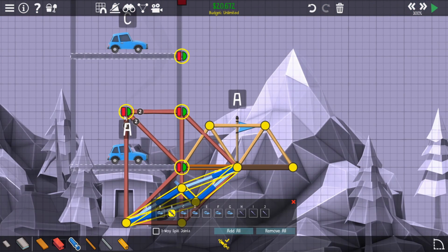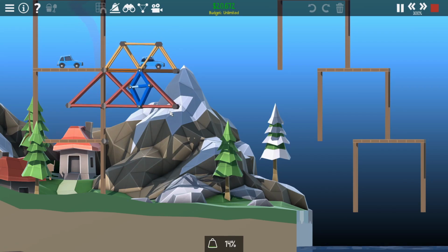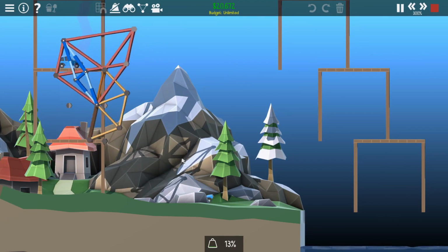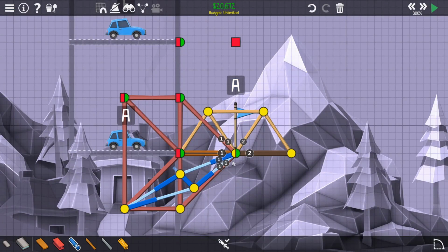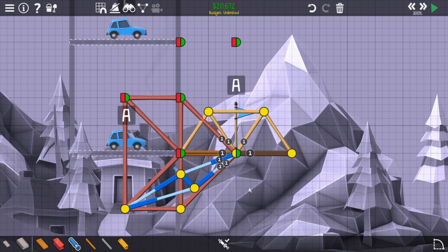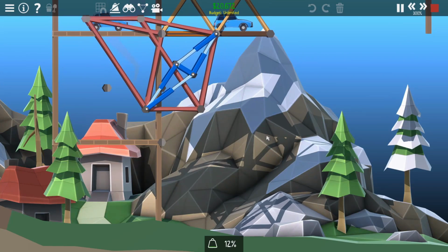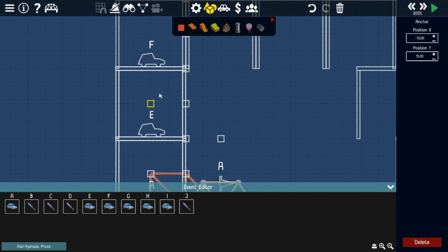At the top, it needs to latch with 2 points so that it can grab, and then the hydraulic can re-expand and push out the extending mechanism again, allowing it to effectively reset. So here I have a second split joint in the top. I'm going to be using that to grab at the top of its motion, as you'll see here, and then it'll push back down, expanding it out. And now it's fully reset, ready to go again.